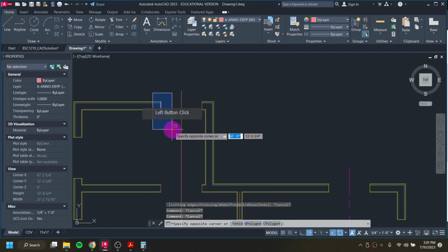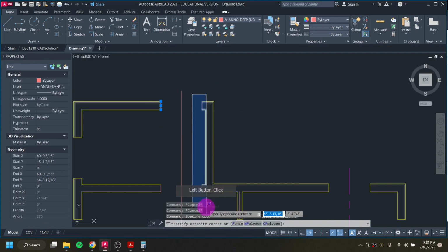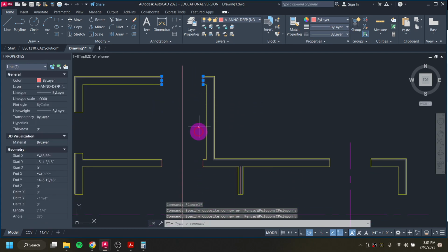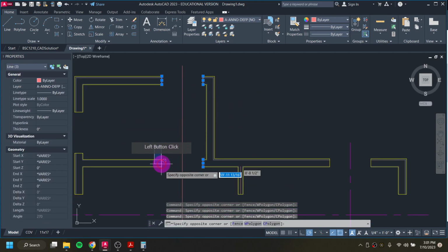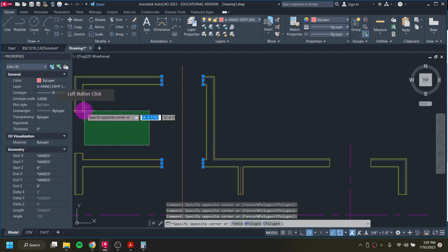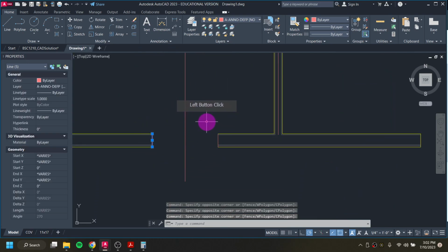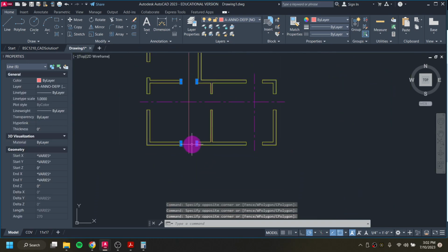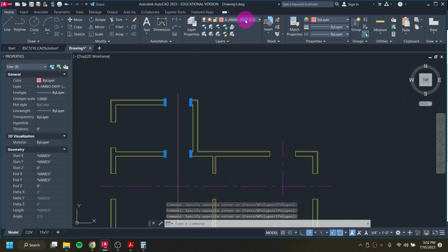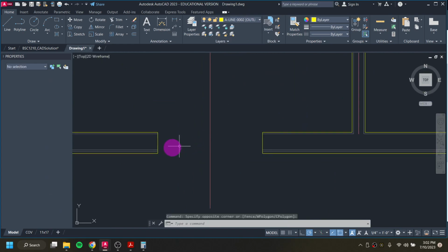And we'll also then highlight all these little guys, which I don't want to do too many big sweeping boxes, especially when I click and go this way. So remember, when you click and go to the left, you get this cross selection. We want to be real careful about switching the layers of things we don't want. So I've got all of these little guys. I'm going to switch them to line 2, the yellow layer.